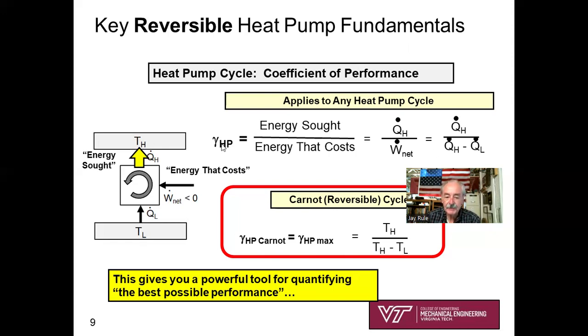You can derive gamma, the coefficient of performance, is Q̇H divided by Q̇H minus Q̇L, all with dots, okay? And you remember in your mind that for a reversible cycle, absolute temperature is proportional to heat transfer. So you've got TH divided by TH minus TL, as long as you remember to keep your temperatures in absolute temperatures, degrees K or degrees R.